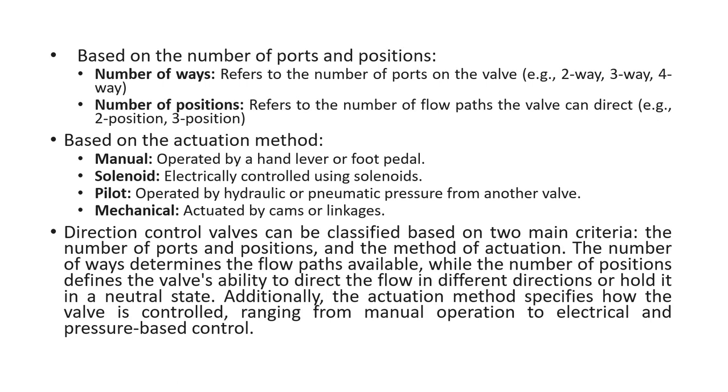Pilot is operated by hydraulic or pneumatic pressure from another valve. This valve is operated by another valve. And the fourth one is mechanical, actuated by cam or levers. By using a cam or levers, actuation of the spool of the direction control valve is also possible.